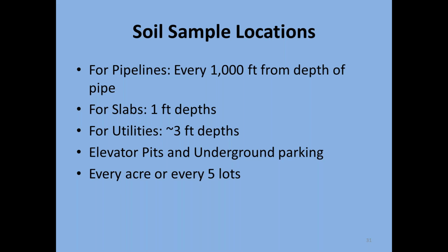And preferably, you don't want to mix soils. If you drilled from finished grade down to 5 feet, you don't want to send a mix of all of that, 0 to 5 feet, to the laboratory for testing, because it's going to be a diluted sample.